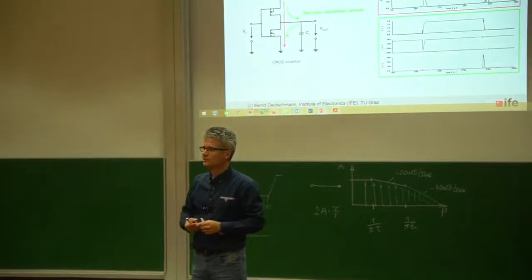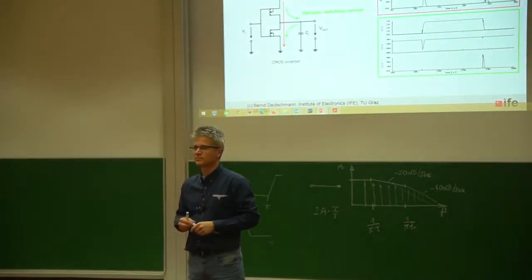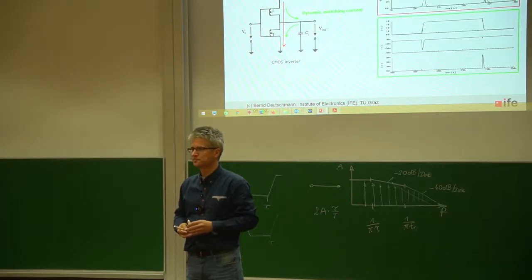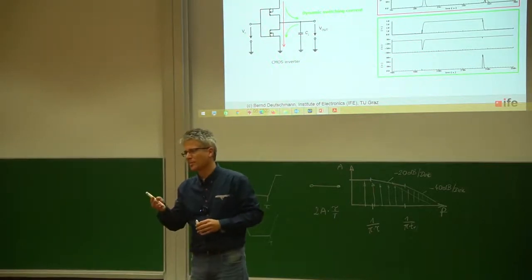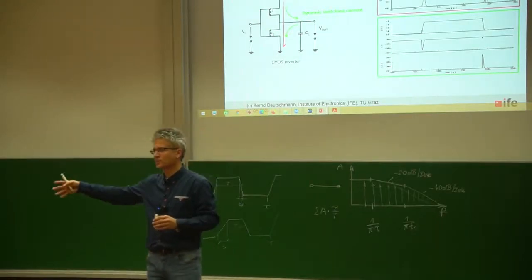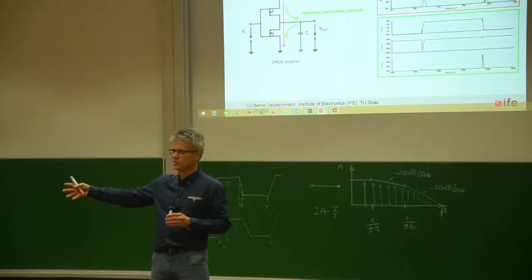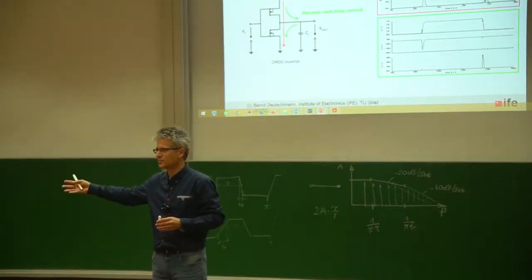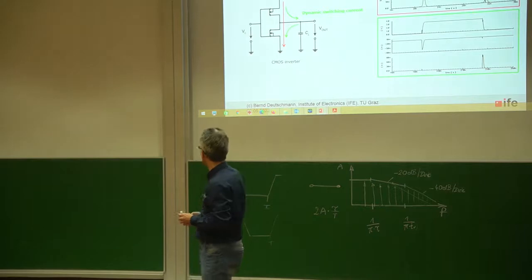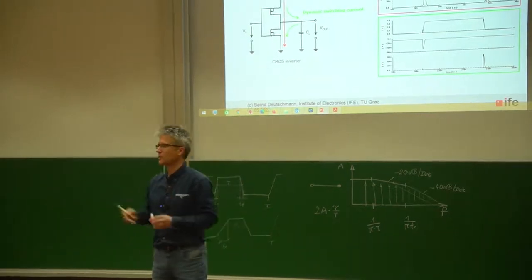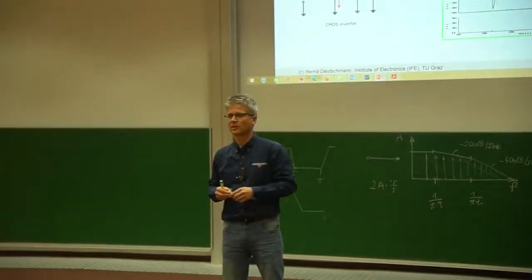Any other ideas? Rise and fall time, crowbar current. What about this dynamic switching current? So we have to charge up an external capacitor, and we have to discharge this capacitor. Well, we cannot get rid of the capacitor, this is there. Maybe we can reduce the size of the capacitor by defining that at this output only a capacitor of this value is allowed.